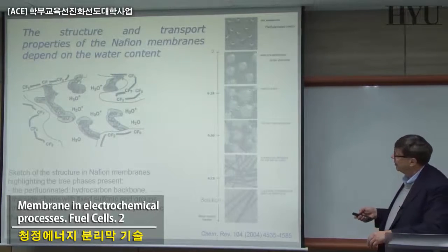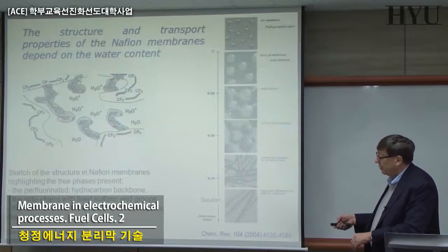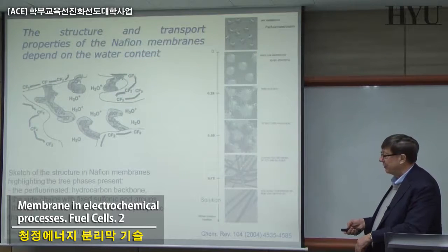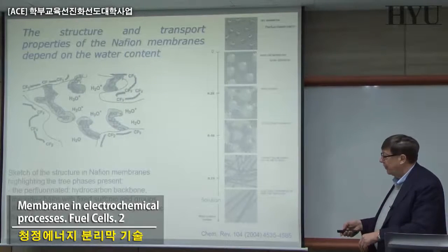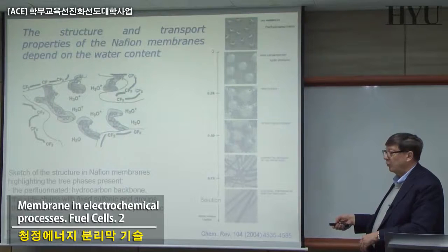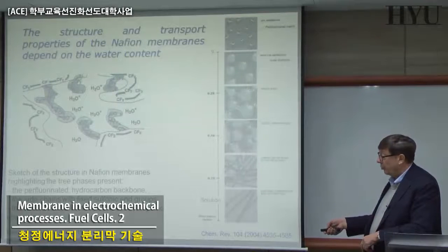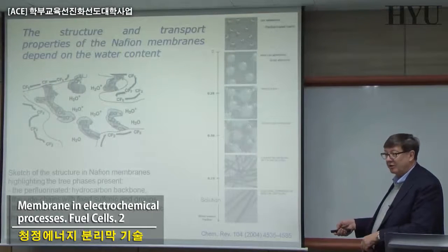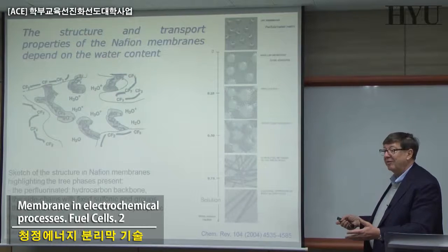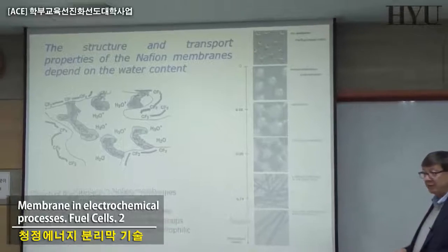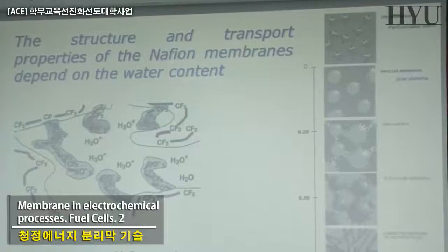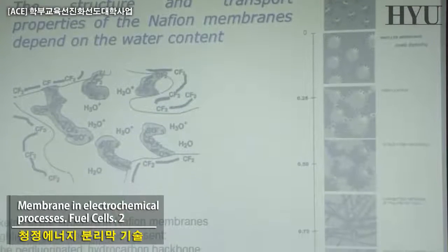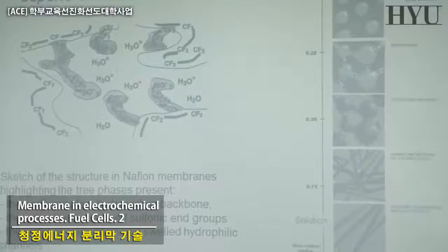You see here a typical structure of Nafion in which you can identify three different phases. One is the perfluorinated hydrocarbon backbone, that's the structure. The other one is the side chains. We see sulfonic groups that can be ionized and give the H+, and the water or water-methanol swollen hydrophilic channels. There are a lot of these free volume channels between the long chains present in the system, and that is giving benefits in terms of proton conductivity when water is present.